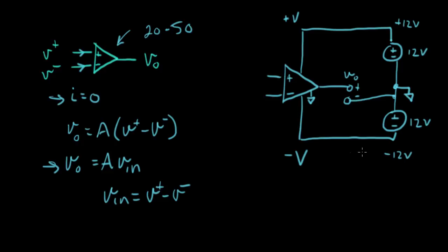What we're going to do is assume that all of this stuff is always hooked up, and we're just going to use an even simpler symbol, just the three terminals like that. You'll know that all the rest of the power supply is hooked up that way. The thing to keep in mind is there's a large minus voltage, there's a large plus voltage, and the ground node is right in between. So positive voltage is high on the page, negative voltage is low on the page, and V out can go both positive and negative around ground. So that's your voltage framework to keep in your head.